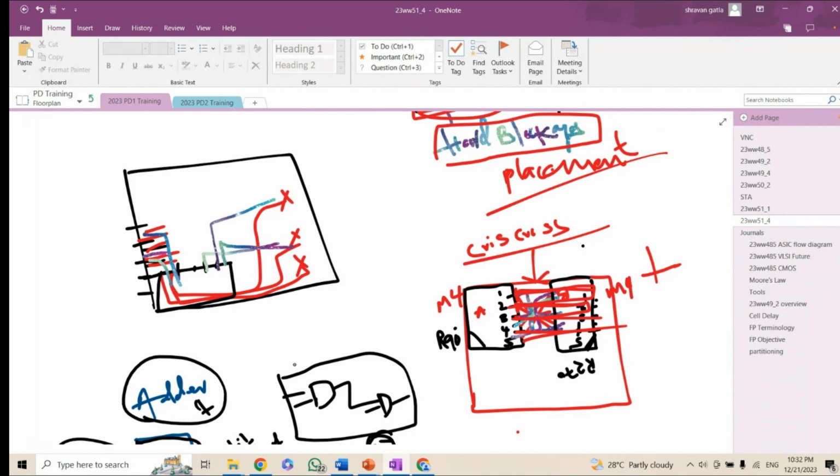Like we just discussed, right? The macro pins are obstructing communication with the standard cells. So it is more about your engineering judgment, how well you place the macro. Maybe someone who doesn't know macro placement will place it here.